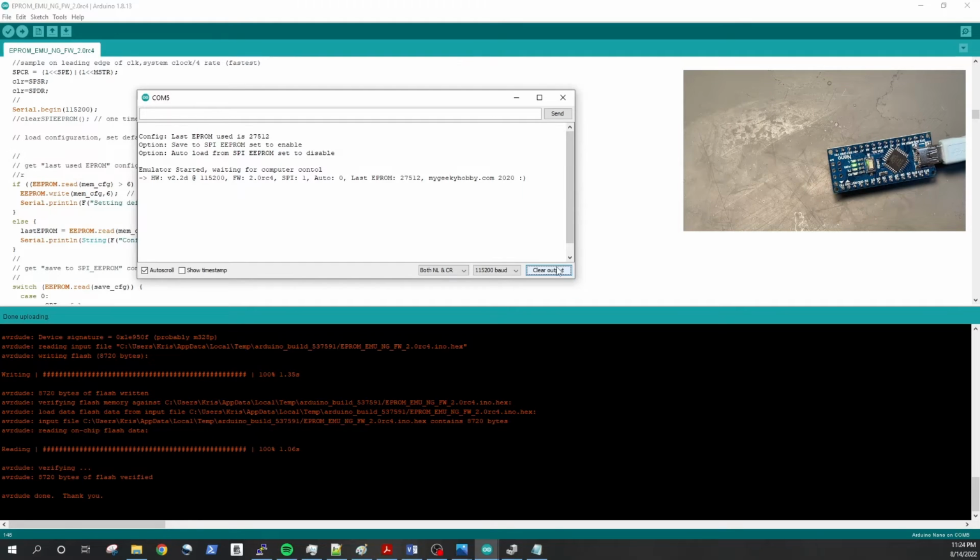So that concludes the video and concludes our efforts fixing this Nano. It might not always be worth your time and effort fixing it. Of course, you need those CH340 chips to actually perform this transplant. So if you only play around with one Arduino and you don't think you're going to be doing it in the future, it's not really worth it.